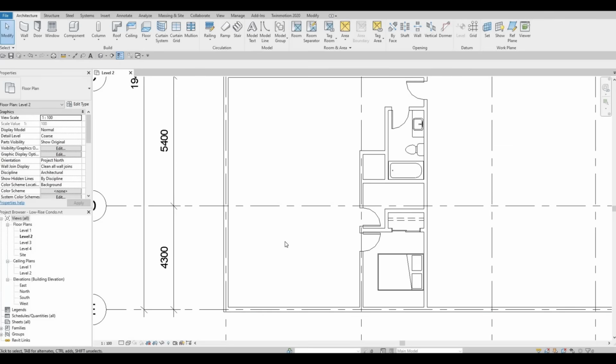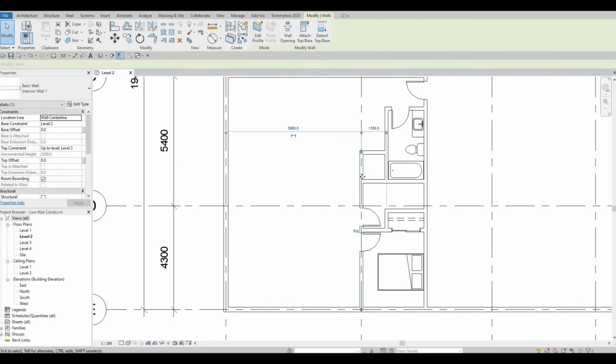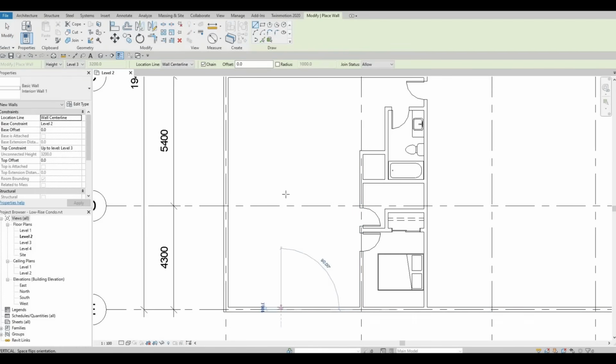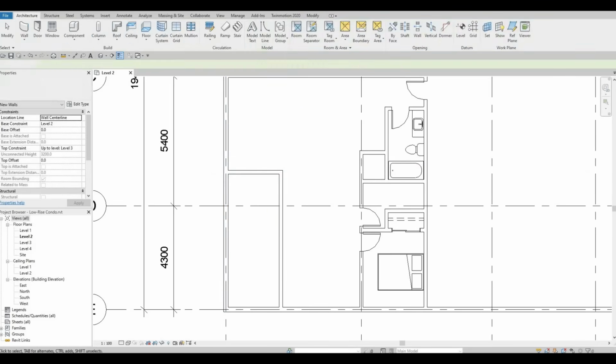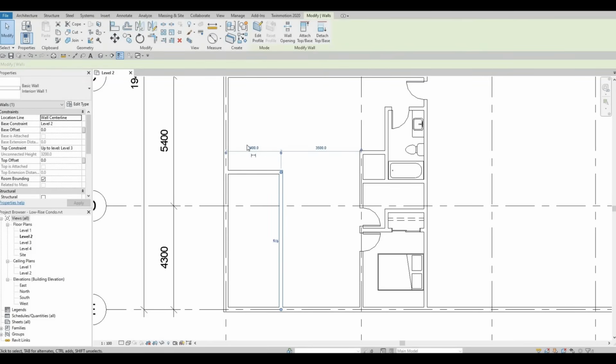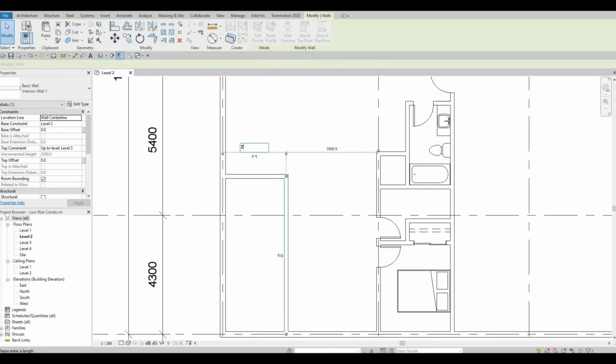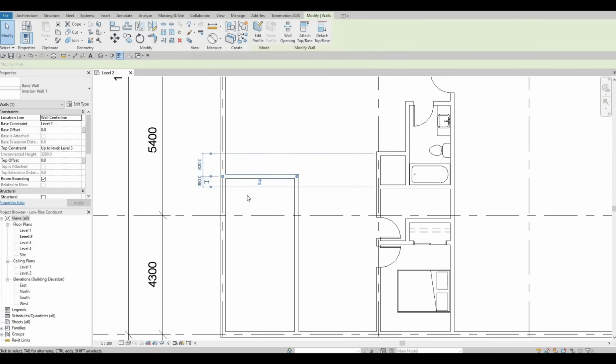Next thing we're gonna do, we're gonna add in another wall here. This is for the master's bedroom. So select the wall, CS, create similar, all the way up, and then let's close this. After that, this one needs to be at 2800. And then this one will be at around 4200.